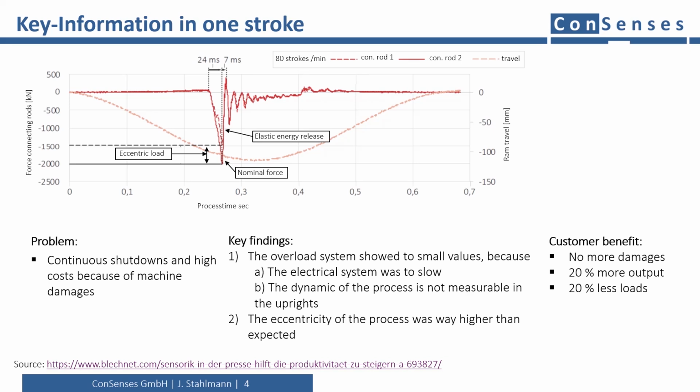After the cutting, the whole ram flies vertically downward and applies a massive tension stress in the region of 500 kN in the left and the right connecting rod. Then the whole system oscillates. The backstroke applies small tension forces and leads to oscillation in lower frequency.